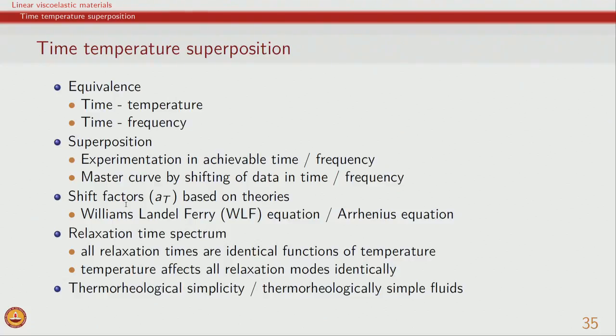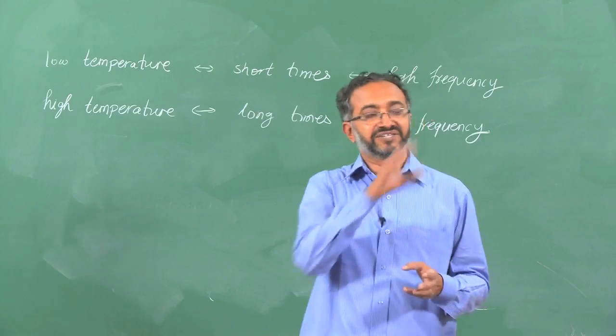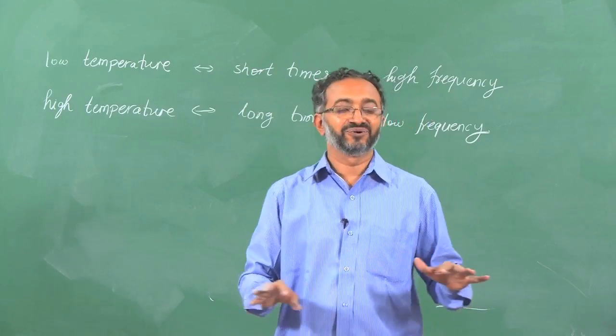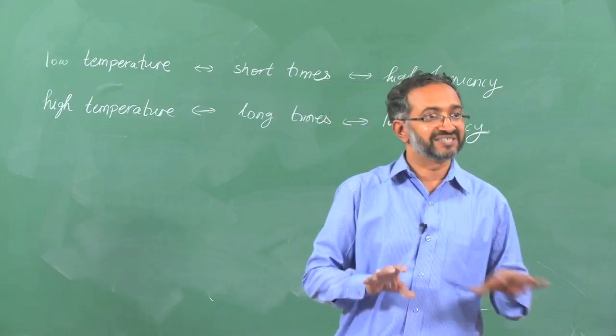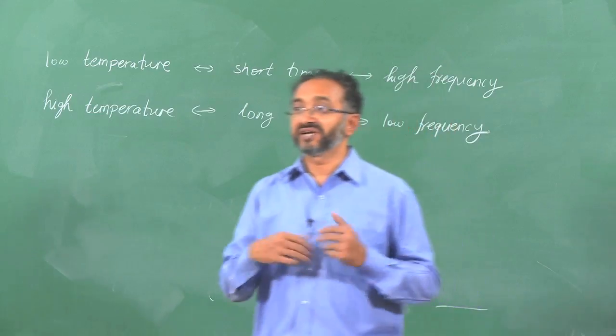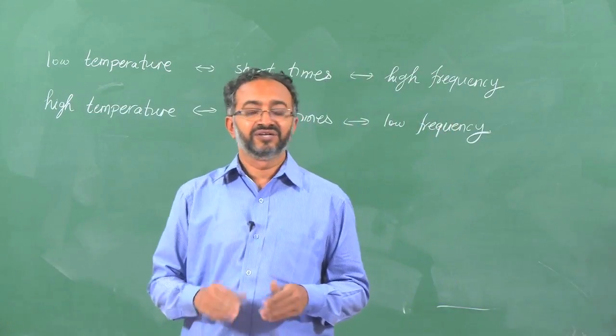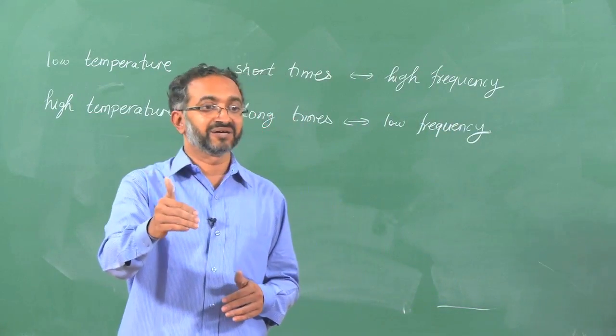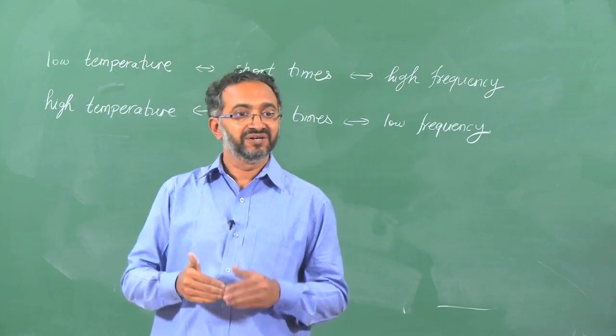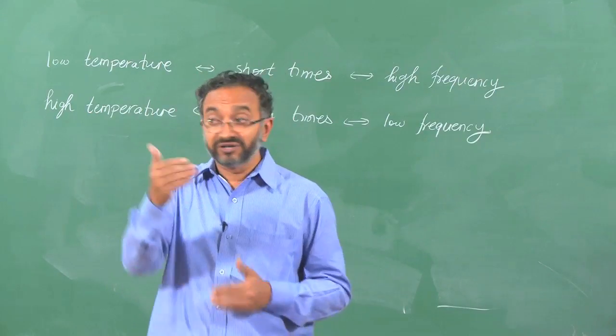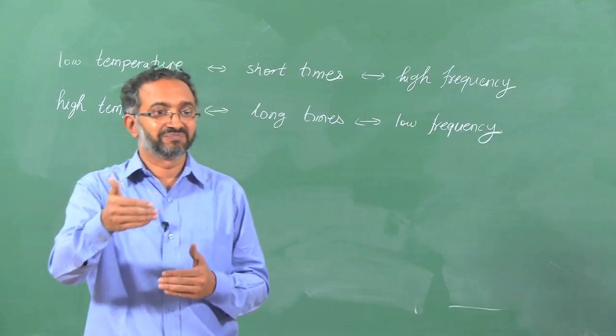First of all, the master curve has to be constructed. If the master curve itself is not good, then you clearly know that the material is undergoing some changes with temperature. So let us not even attempt time temperature superposition. Then you should not do tests at some other temperature and try to make deductions about lower temperature, because anyway your material is different at two different temperatures.